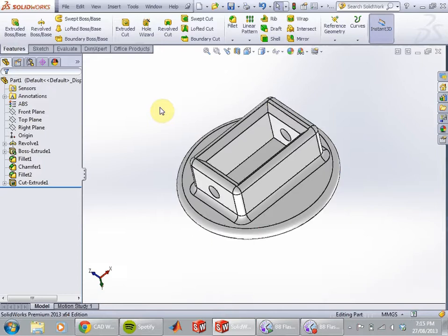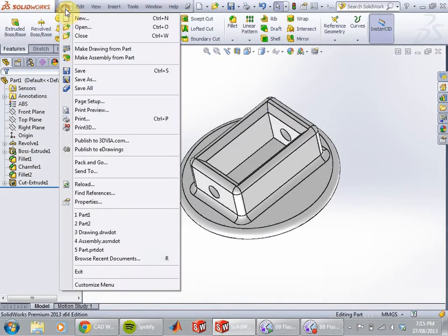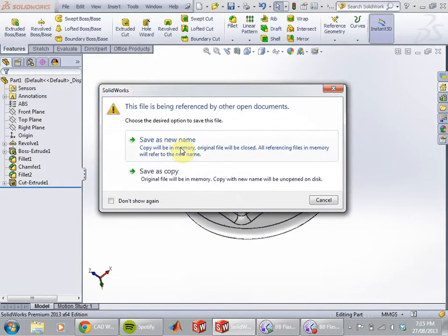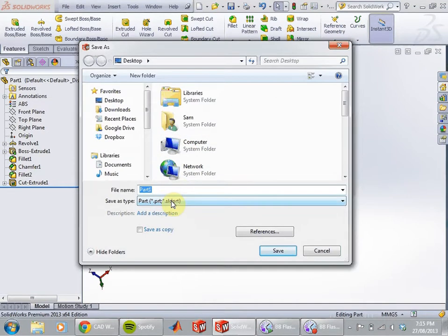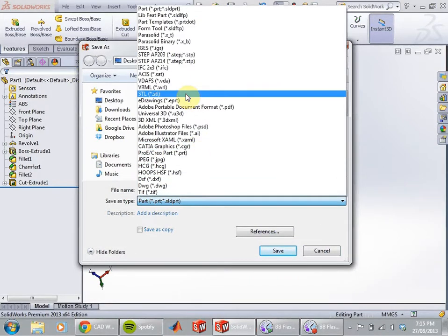So say we want to 3D print this. We can go File. For now, just continue what you were doing. I think it's something we can add in the last week. This is for if you want to 3D print. What you need to do is save it as an STL file. Find it somewhere around here.